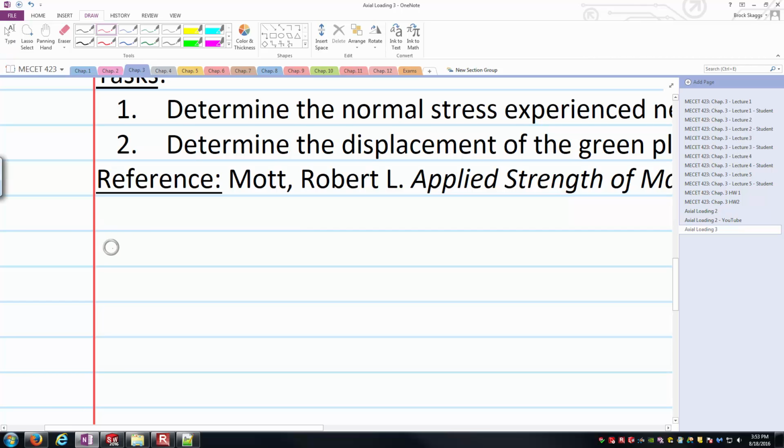And so here I'll draw my free body diagram, and we'll call this section 3. Okay, so now we've got to draw some sort of representation of what I removed. Well, there's my cut surface. We'll say there's the very bottom of the shaft itself. And so one thing I'm going to do is I'm going to say, well, I'm trying to figure out the normal stress, so there has to be some internal force that this section is carrying.